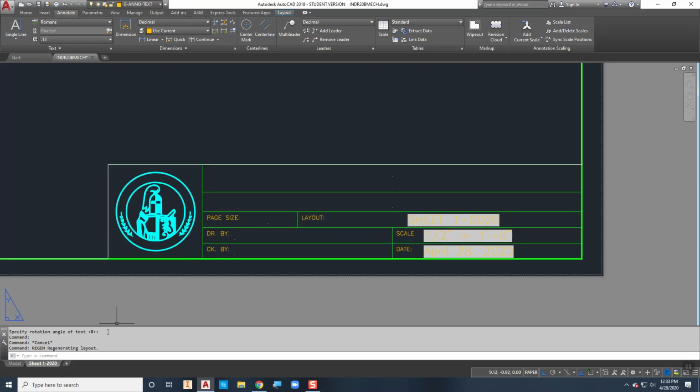And so you could have several different sheets, and you could identify them what they are down here. It could be electrical drawings, it could be pneumatic drawings, it could be whatever, and it will automatically put that name up here. Okay. Next, we're going to move over here to drawn by. So I want to put in a field for drawn by so that you don't have to type your name in over and over and over again. So we'll go in here and we'll say, of course, single line text.